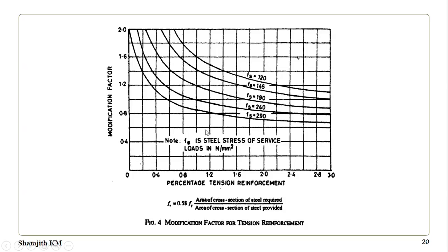We will be drawing an imaginary line in our mind. It will be passing through this position, and 205 will be coming through here, and it will be meeting somewhere here. So we will be checking what is the modification factor here. This is 0.8, this is 1, this is 1.2, and this is in between. So we'll take the modification factor in tension, Kt, as 1.1.